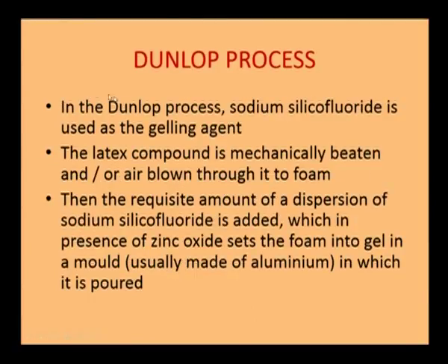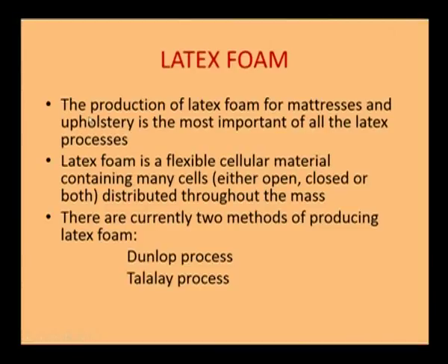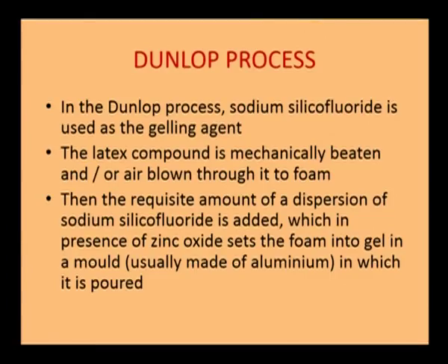The Dunlop process has a gelling agent like sodium silicofluoride added in the course of the process, along with zinc oxide. In the previous session I told you about zinc oxide, an important additive for compounding, and this zinc oxide is again coming into the picture for manufacturing foam.